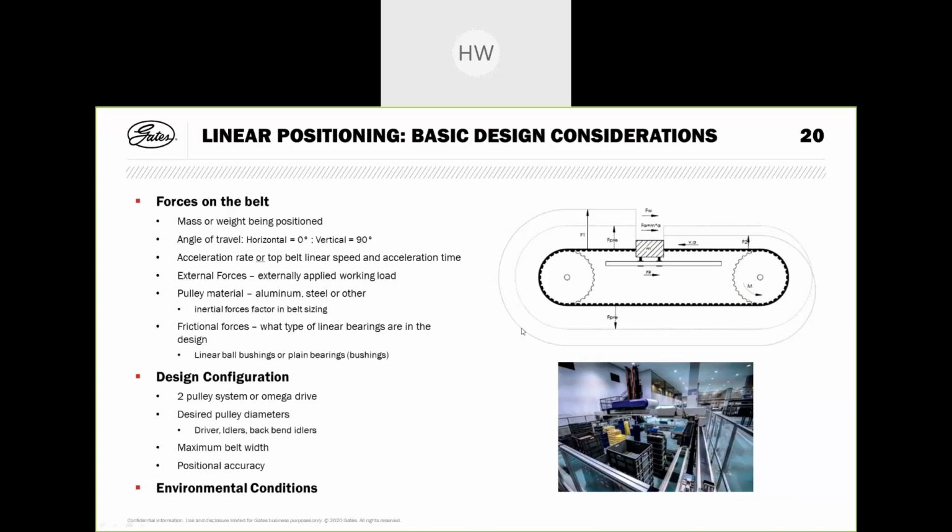Also here, there is a slight difference between a two-pulley drive or an omega drive, and we have to respect the design envelope, desired pulley diameters, maximum belt width, and positional accuracy, and of course also the environmental conditions.